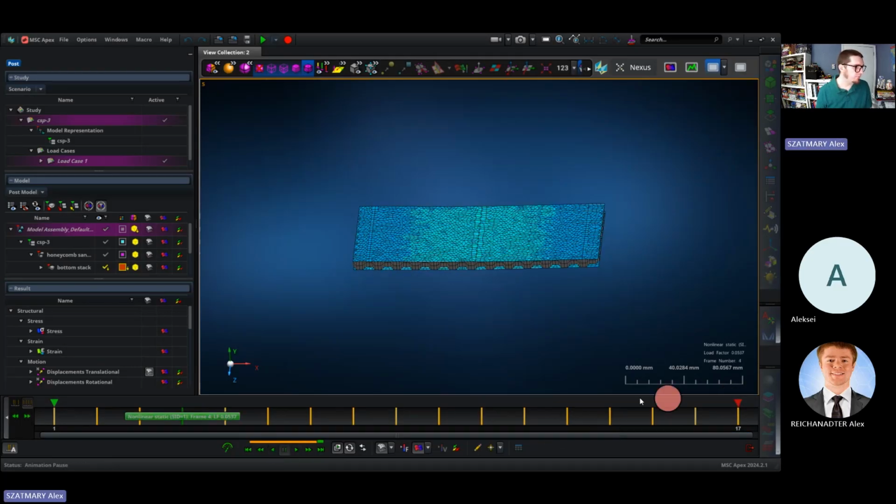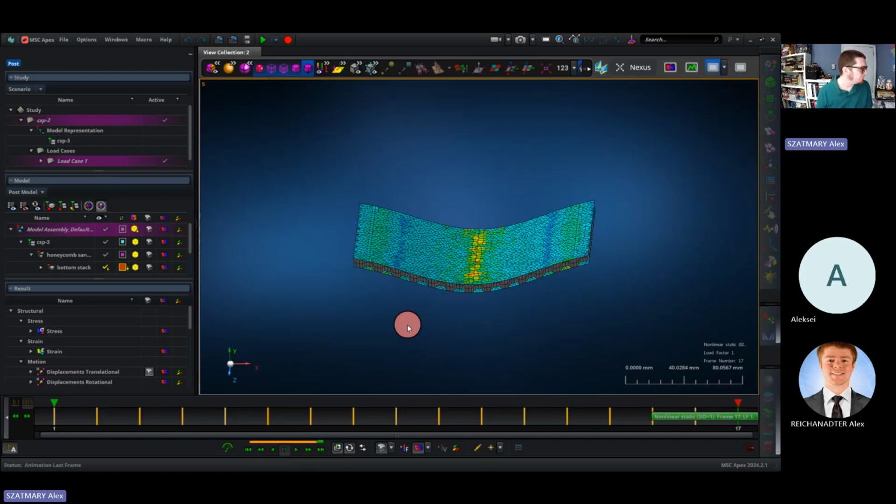In this case, I have all of my steps available to me, but if you ever see this red triangle, maybe over there, you can just click and drag it all the way to the right, and that will let you look at all of the load step results. And I'm actually going to pick this point, because where we get at the end of the simulation is the most relevant. Or you can click this button here to go to the last frame.